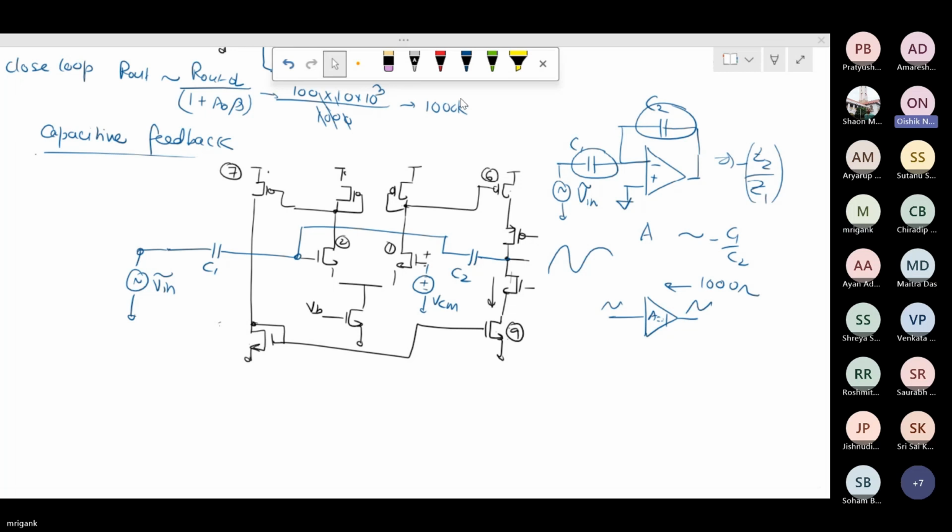Yes, sir. For MOSFET number 2, for its biasing at the gate, the common mode voltage needs to be applied. But we can't add it before the capacitor because it will be blocked by the DC. Yes, so the capacitor will block the DC, so there is no way to have a DC current. From the DC point of view, this DC voltage V out DC will not reach the gate of M2. So M2 is a floating node.